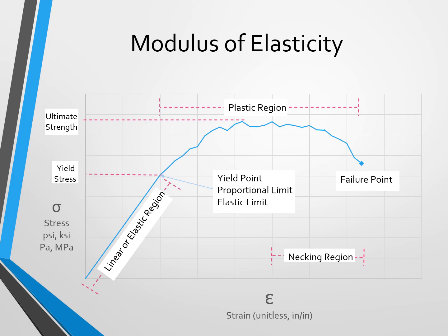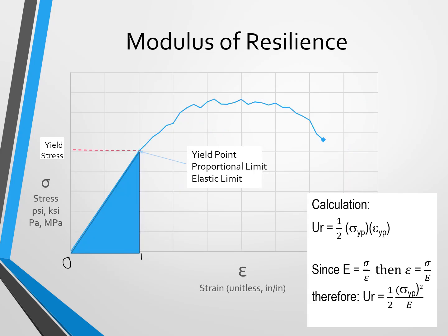All right, so far we've seen how to calculate modulus and how to decipher yield strength and ultimate strength from a stress strain curve. We can also get the rupture strength in the same way, just reading it off the graph. Here's my rupture strength. And then there are a couple other properties that we can also estimate using the stress strain curve. The first of these is the modulus of resilience. This is the total energy that can be absorbed per unit volume without creating any permanent deformation. We find this value by integrating the stress strain curve from 0 to the elastic limit.